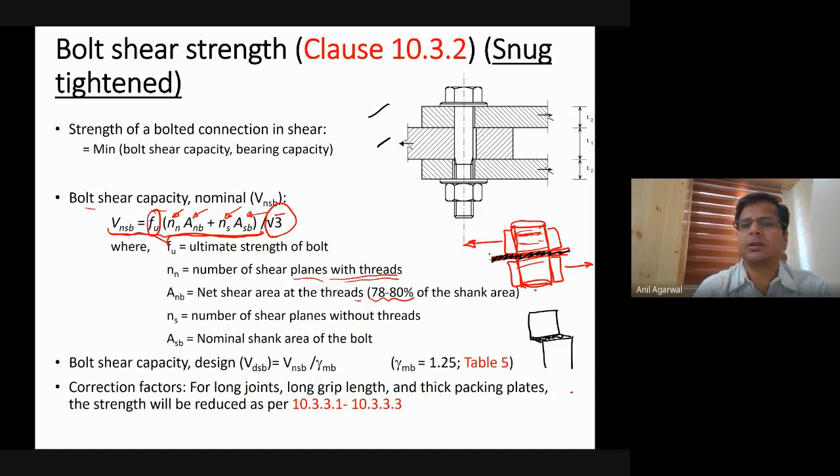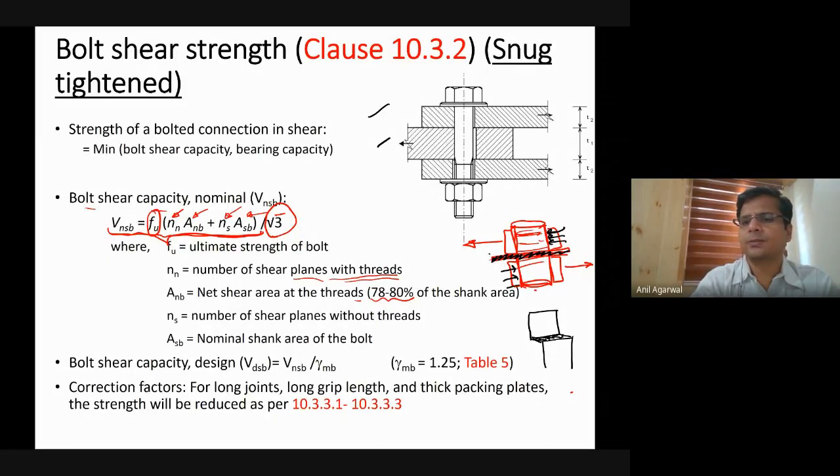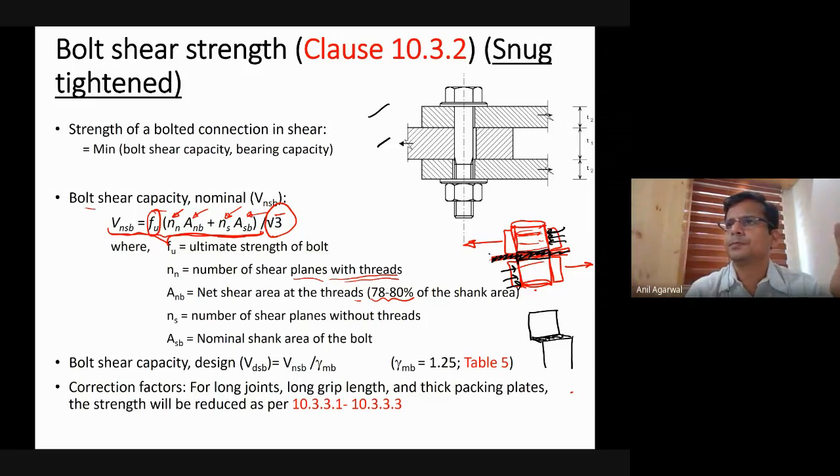So in this particular case, if you see the forces, let's say it is being pulled this way, so forces are applied in this plane, and then here the forces are applied like here, like so. Okay, so the portion that is without any external forces is a very narrow band. So the entire deformation, the entire failure, yielding, damage, whatever you want to call it, will be confined to that plane only.